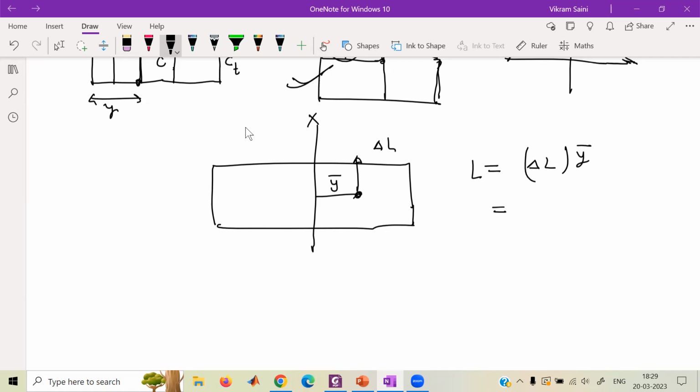Okay. Now, how do I compute the change of lift? This was discussed in one of the lectures, when the aircraft rolls, how much extra lift is generated. So we ended that lecture with the conclusion that whenever the aircraft rolls, because of the side wind, the leading wing, which is going into the roll, let's say if the aircraft is rolling towards the right, so the right wing is going down, so the right wing will experience an increased angle of attack by how much magnitude?